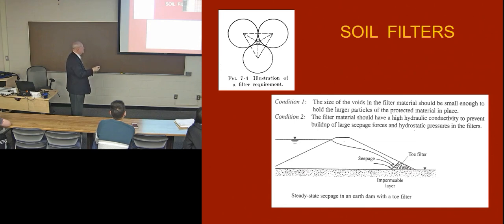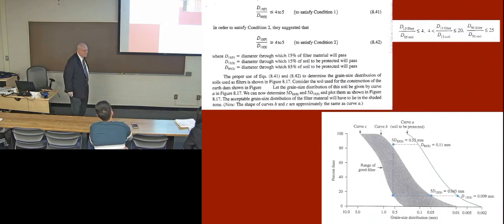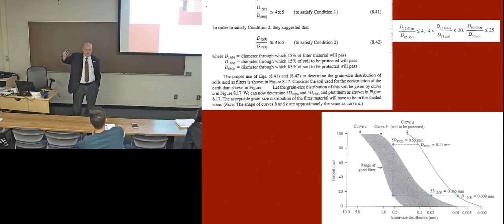The second thing is that the filter material must have a high enough hydraulic conductivity to pass the water without building up pressure behind it. And that is something else we need to control. Well, who did the basic work on this? Who can guess? Who's the father of soil mechanics? Carl Terzaghi made the first suggestions.